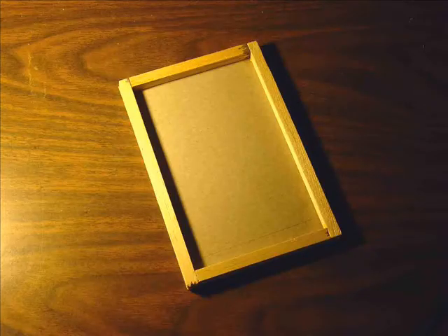Later, we will provide additional reinforcement for the baseboard of the planning model. We will cement strips of 3/8 inch basswood along all four edges of the model. The basswood strips will serve two purposes. First, they will increase the rigidity and flatness of the baseboard. Second, they will simulate the future appearance of the final 20 by 30 inch baseboard of the display model, which will be reinforced with heavy wooden strips along the bottom edges.